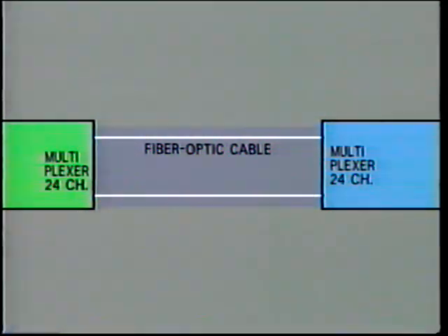In this system, there is no wire connection between telco and the power company, so eliminating any induced longitudinal voltage. Also, there is maximum possible isolation between ground potential at each end, so reducing or eliminating problems of GPR. As you would guess, this system is quite expensive and is not yet in widespread use.